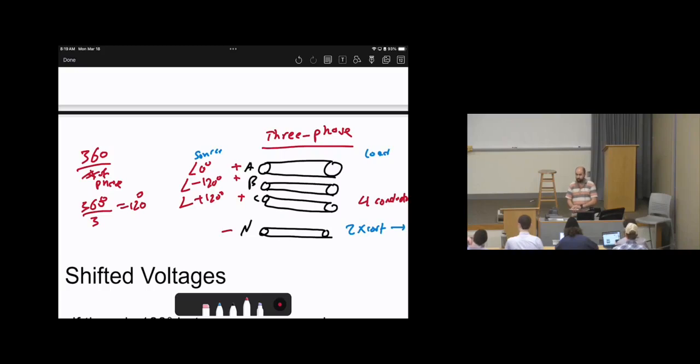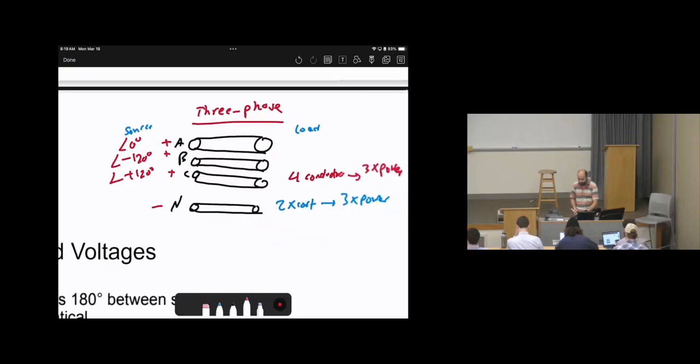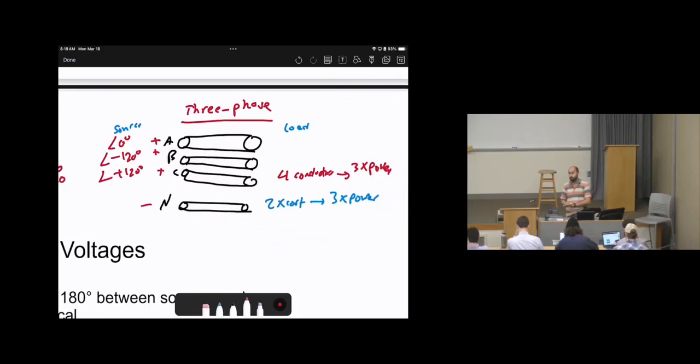Now, with the three-phase, we found life is much easier. We can connect 3 times the power by doubling the cost. And we realize that when we connect power over what we call transmission lines at high voltages, where we will not connect the load, if you transmit the power from one side to the other side, with no load connection, basically at high voltage scale, we can get rid of the neutral and use only 3-phase alone.